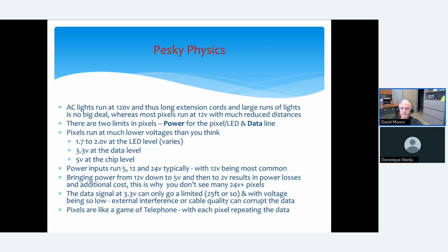In your wire, you have a pigtail, and I don't know if you can see this, it has 3 wires, right? So Holiday Coro invented the X-Connect. We didn't name it, we call it something else, but we came up with the plug and then the wiring standard. And we came up with, of course, the color standard, black being negative in the US and red being positive. And that positive wire provides the power for the chip itself and the LED. Now, we also have a data wire.